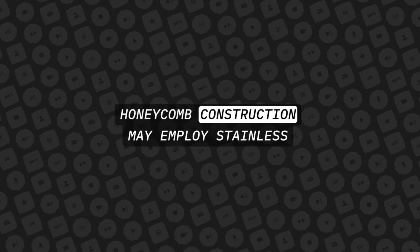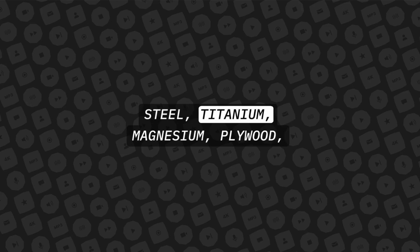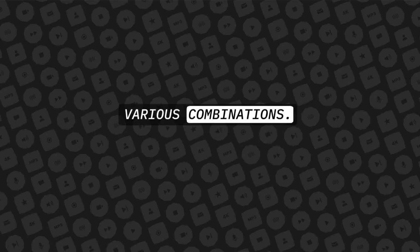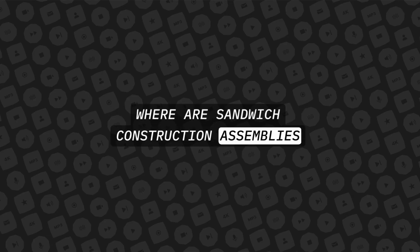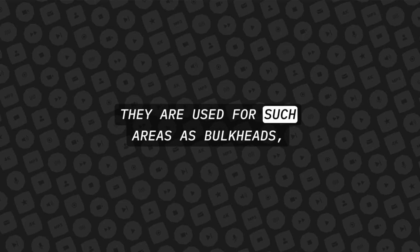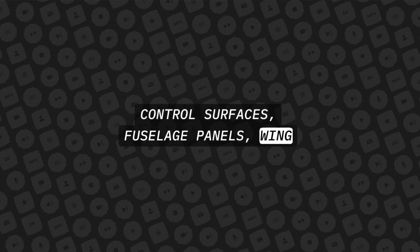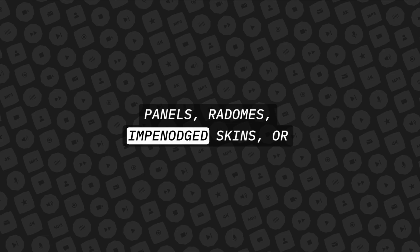Honeycomb construction may employ stainless steel, titanium, magnesium, plywood, resin-impregnated paper, e-glass, nylon, and various combinations. Where are sandwich construction assemblies used? They are used for such areas as bulkheads, control surfaces, fuselage panels, wing panels, radomes, empennage skins, or shear webs.